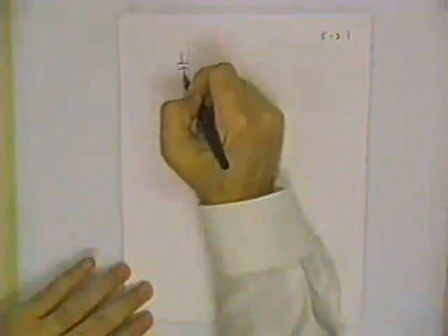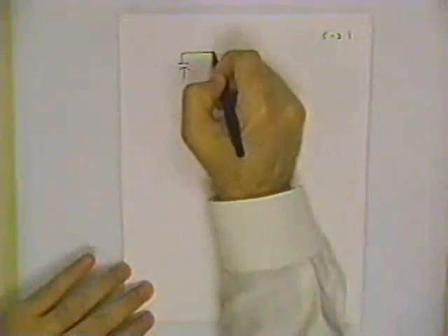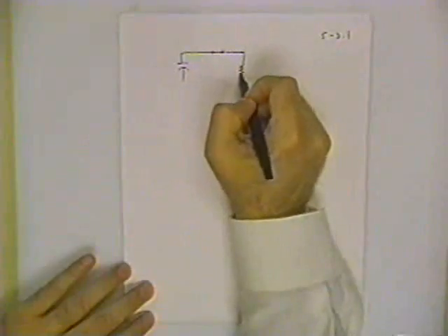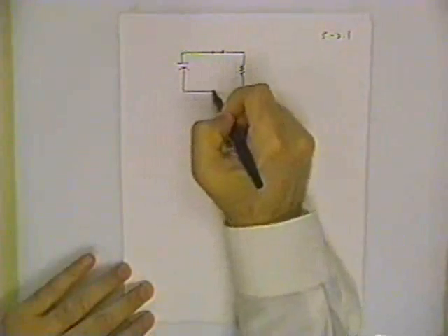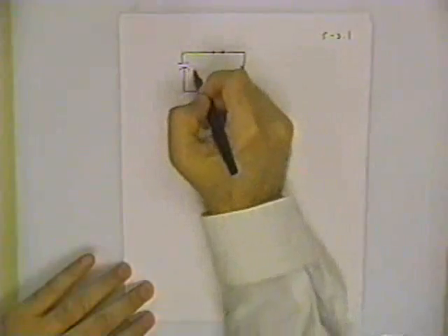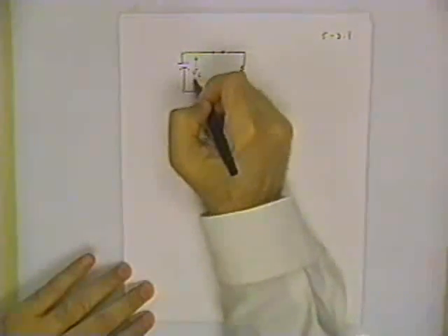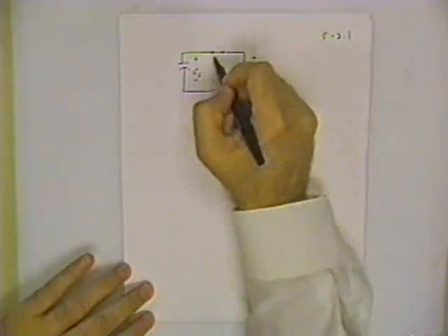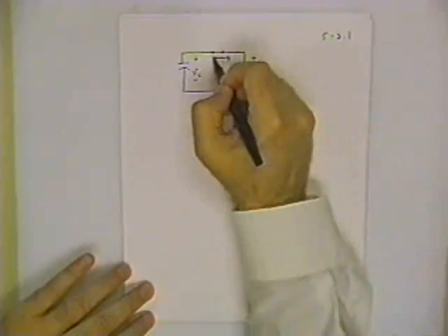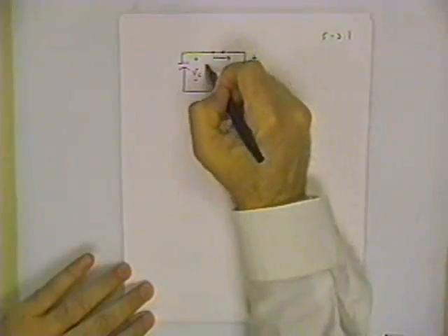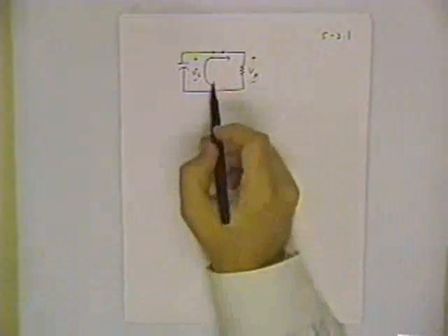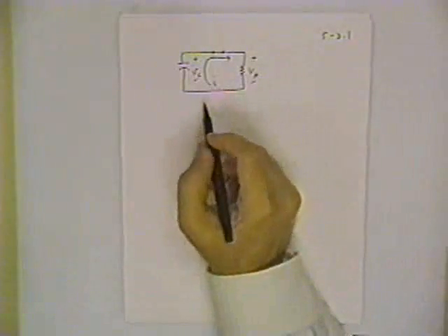So what we do now is write out the Kirchhoff law with the switch closed. You can actually show that it's a closed switch with two little node symbols like that. And what we need are two different symbols for the capacitor voltage, plus to minus, for the resistor voltage, plus to minus, and here's our current. It's a clockwise current going through the whole loop, and we can just call that I. Since it's the same current for both elements, we don't need a special subscript on that.